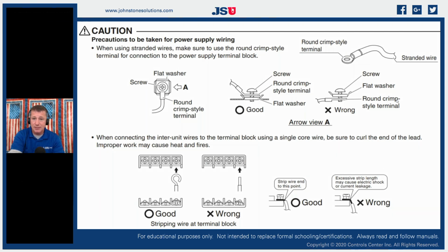In this particular installation manual, which is for a mini split installation, it does have a recommendation of using stranded wire, either for communication or for the actual high voltage. But at the same time, we still need to land that with a solid connection. So even when we're using stranded wire, we still need to be able to land with solid contacts.